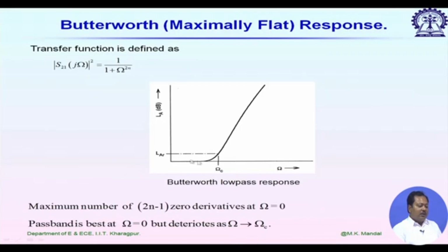But for Butterworth polynomial, we have one advantage. If we plot the group delay variation, it will have lower variation compared to the Chebyshev one. So, for wideband applications, Butterworth should be preferred if we want to avoid any dispersion.